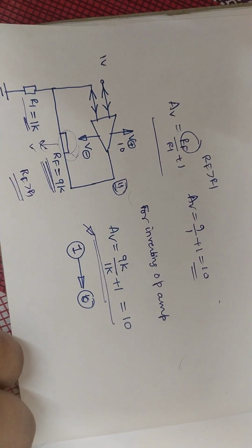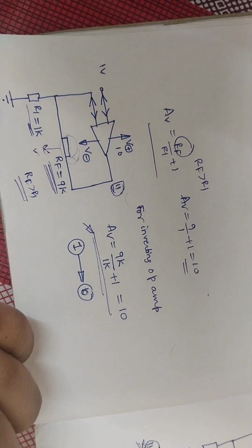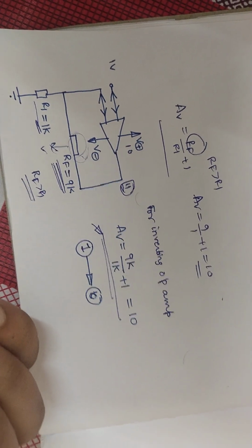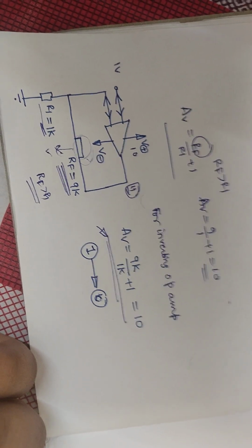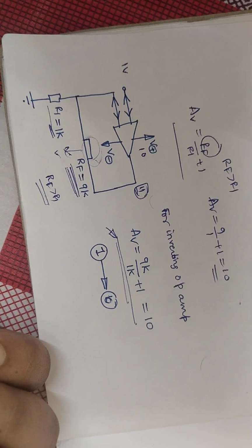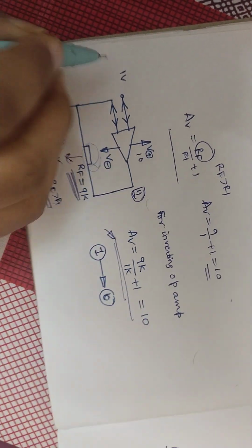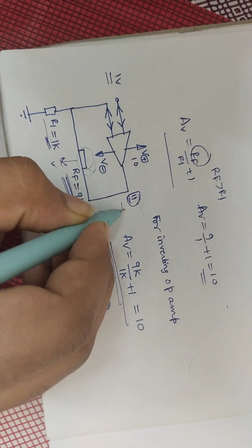These are the basic building blocks of modern electronics, and as we get positive and negative rails, it can feed AC and DC signals about ground. It can handle negative too. Even if we connect negative 1 volt, it comes out as negative 10 volts.